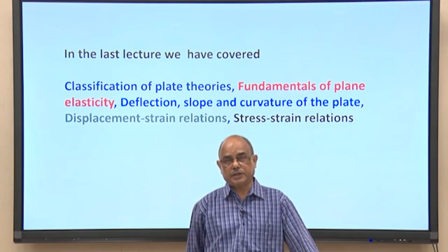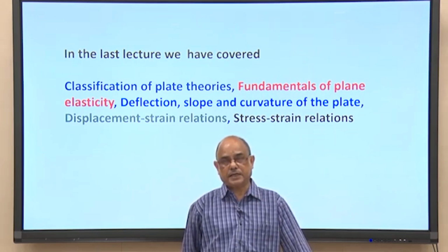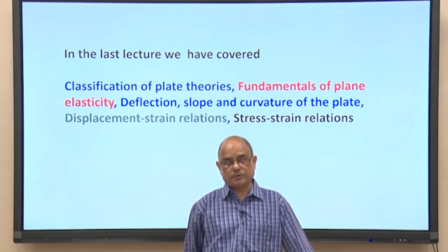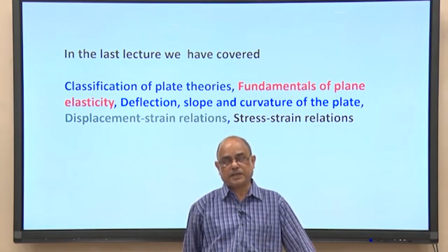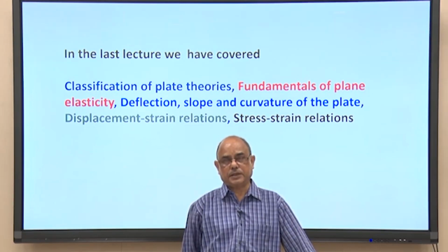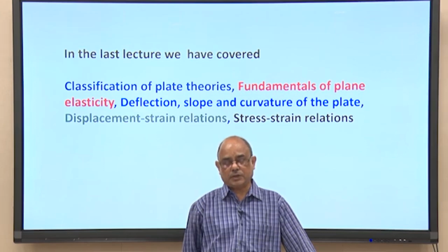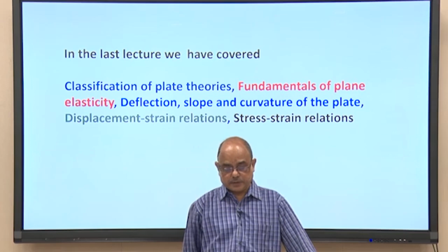I mentioned that if the plate thickness is less than 1/10th of the larger dimension, then the plate is classified as a thin plate. Otherwise, if the thickness exceeds 1/10th of the larger dimension, it is called a thick plate, and thick plate theory has to be modified based upon the shear deformation criteria.